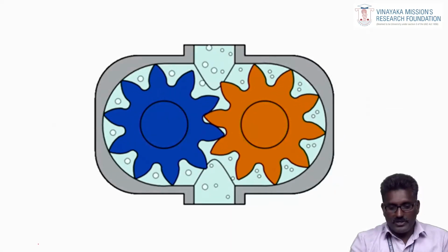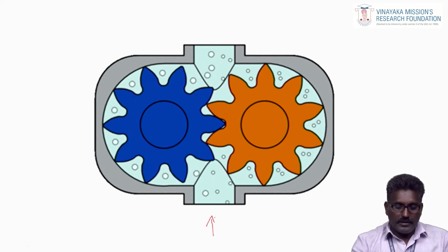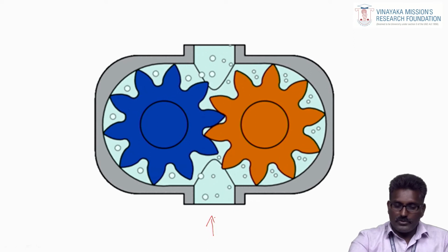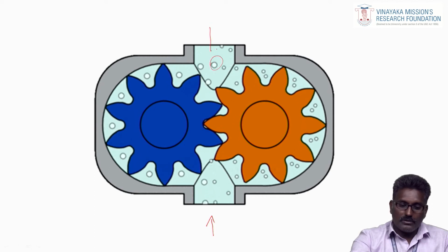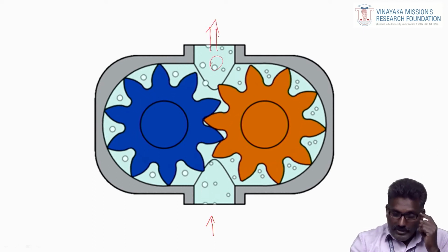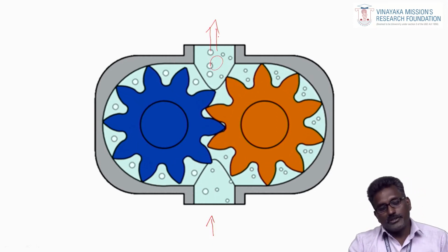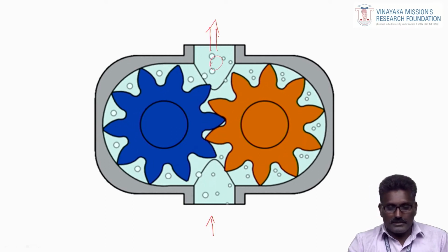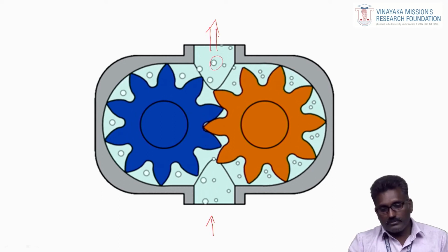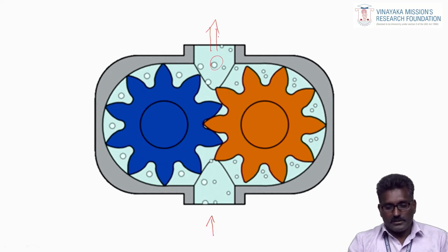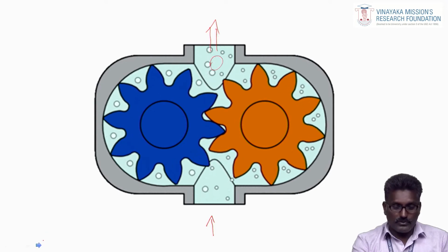You see this animation of the working of this pump. The fluid comes in here, and due to the continuous rotation, the fluid is delivered here and moves out. As I said earlier, if we do not connect any load, the pump rotates freely and consumes very little energy. When we connect the load, the pump produces pressure, and we use this pressure to do some useful work.